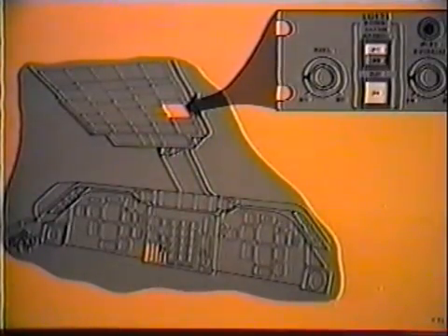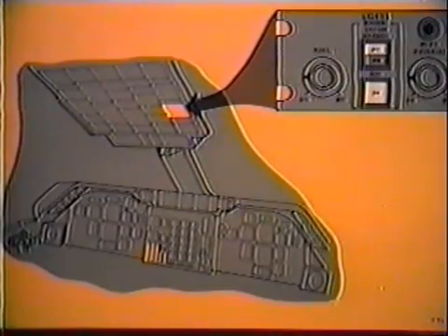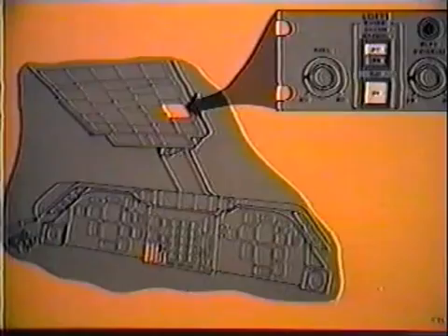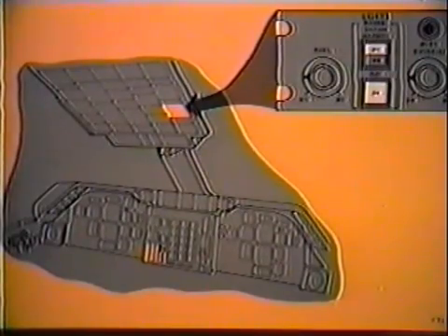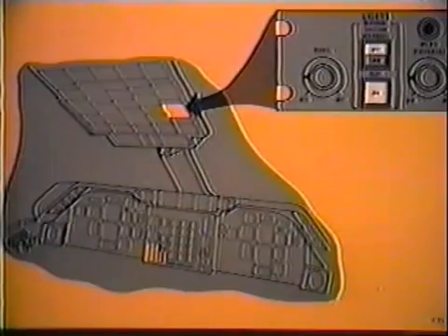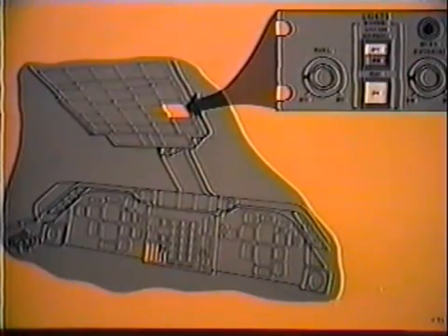The Warning Caution Advisory Light's test switch serves two functions. One is to test all the forward and overhead panel lights and the pilot's annunciator lights. The second function is to recall any light on the pilot's annunciator panel which has previously reset and for which the fault has not been corrected. This light's test will automatically be terminated at the end of 5 minutes to protect the lights from overheating.